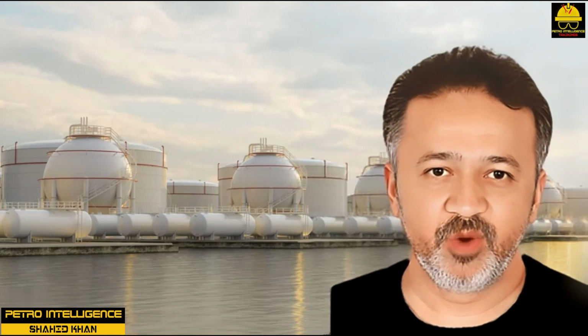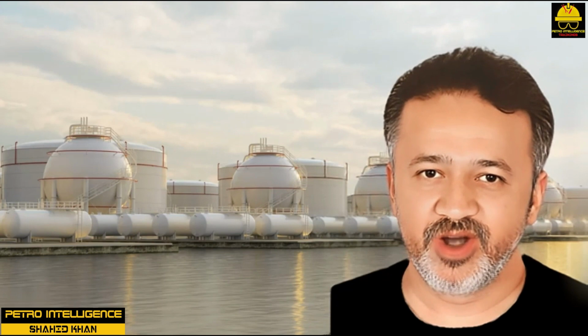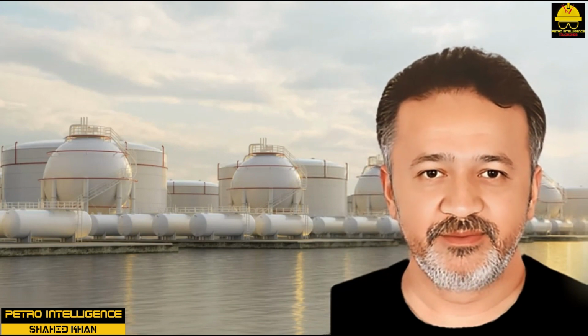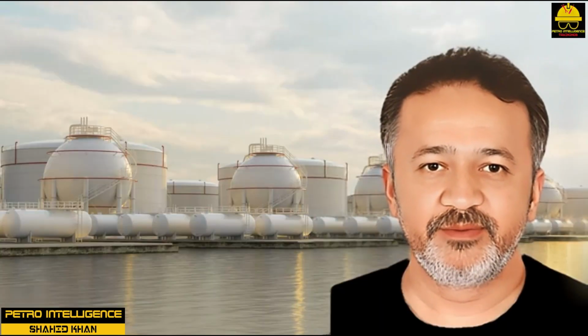Usually, a drum is supported in the vertical position on a concrete foundation or in the horizontal position on two or more concrete piers. Spheres, as we use the term, are pressure vessels shaped like a sphere and supported above grade on large tubular columns. A sphere 65 feet in diameter will have a volume of 25,000 barrels. A sphere has a more economical shape than a drum for the storage of liquid under relatively high pressure. Spheroid tanks are similar but have a somewhat flattened top and bottom.